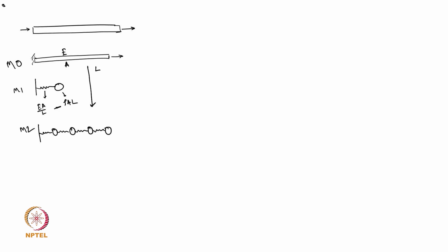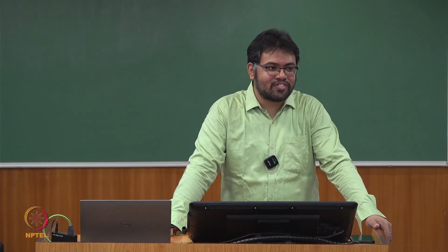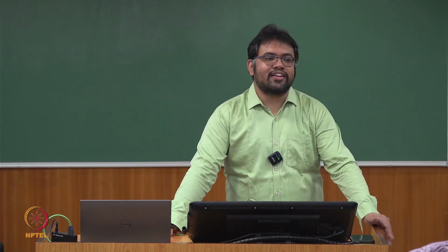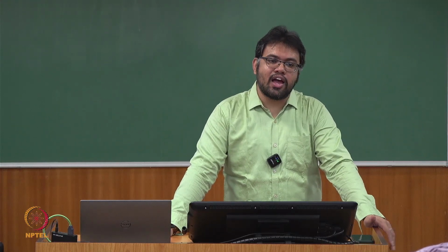Very simple. Now if I think of model 2, let's say it's a 4 degree of freedom system. So how many natural frequencies can be possible? 4. And they will correspond to the 4 modes. Okay. Now how many natural frequencies can you expect from the original model? Infinite, exactly, because it's a continuous system. So you can see that these are always approximations. You are not getting exact things. You are approximating the modes.